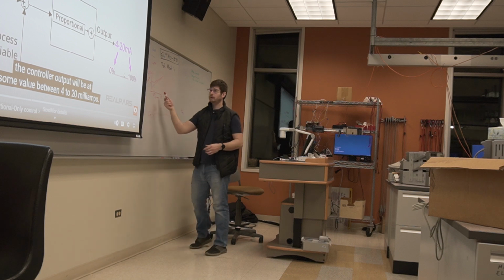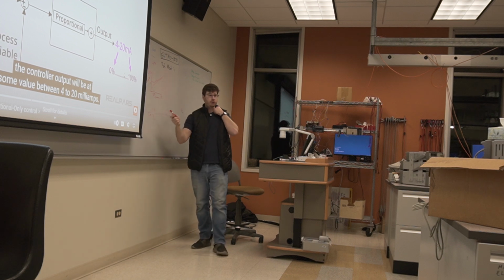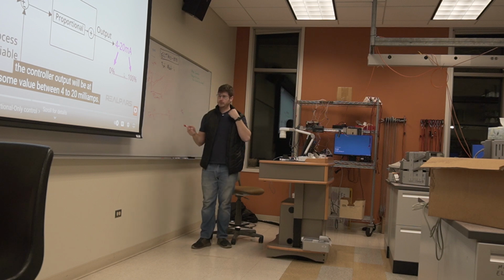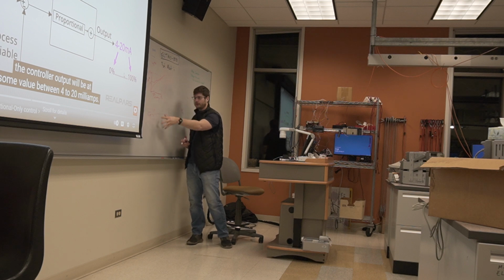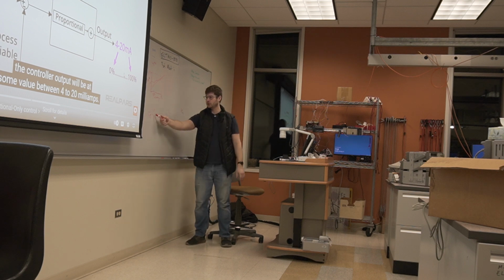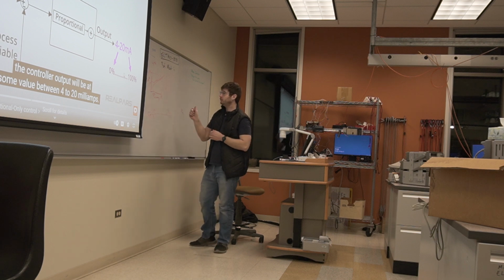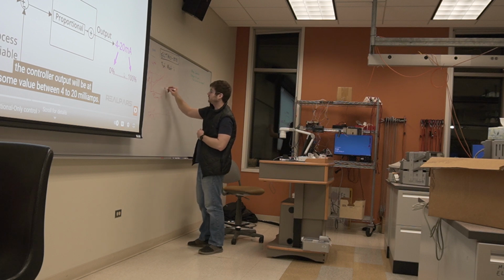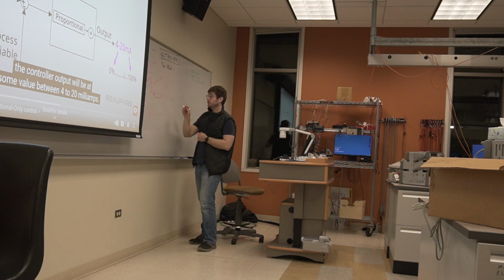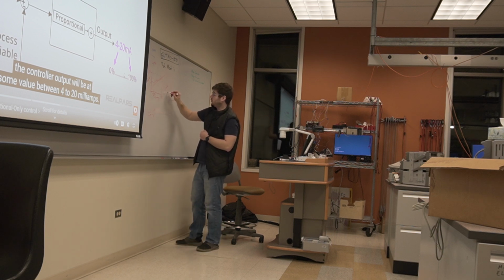So this is problematic. We want to make sure that our sensors are reporting things to us in a way that won't be degraded by the environment, right? Interference can mess with this, the drop of the line can mess with this, all kinds of stuff. However, if we use current instead of voltage, this is still temperature, things change, okay? So what they've done is they've standardized this.